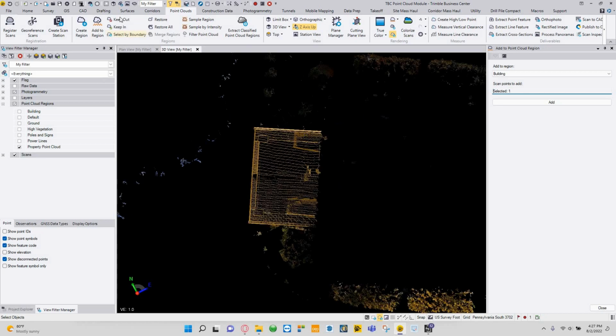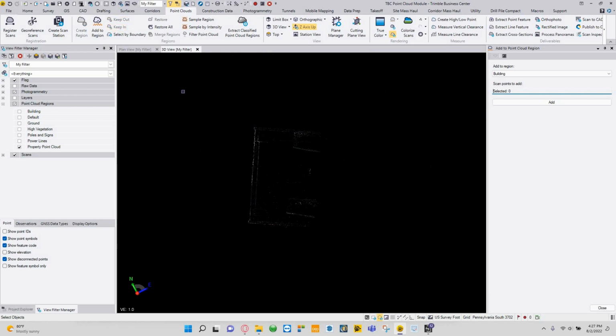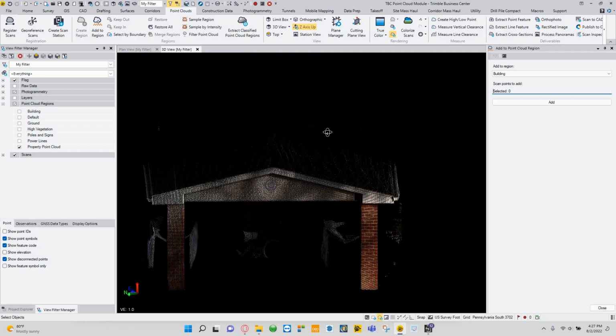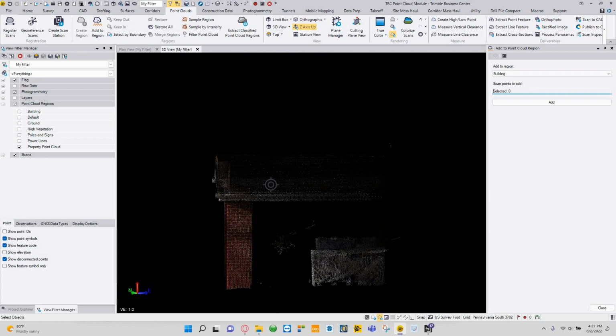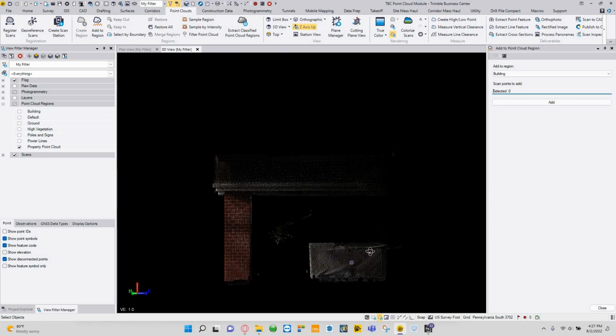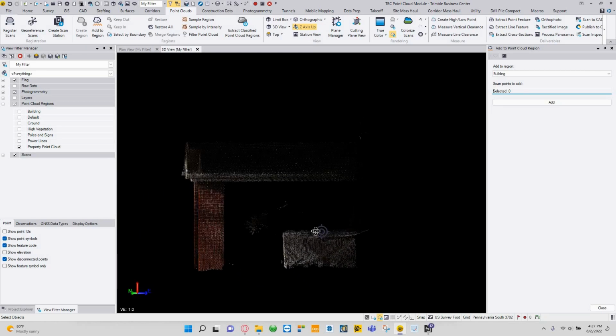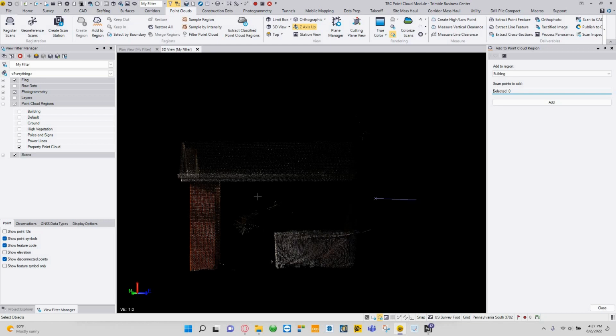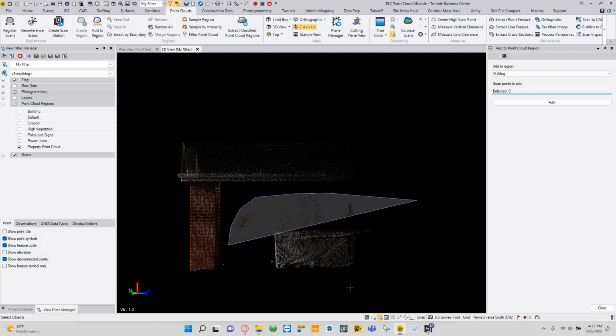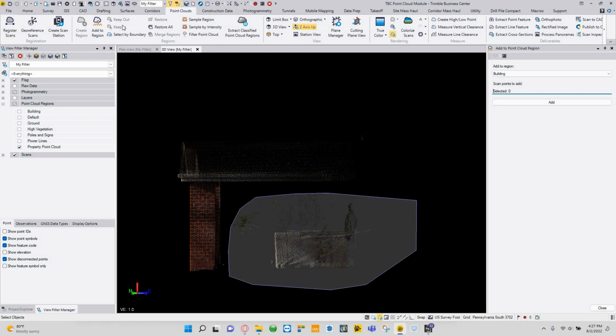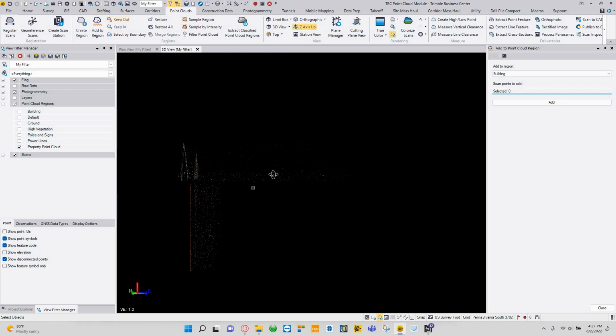Now this is where we start employing the keep in and keep out. So I want to keep that particular section in, and as I rotate around, I do not want to have these two, looks like pallets or something, and then plus we have some people underneath there. So what we can do here is draw a box around them, and tell that to keep out.